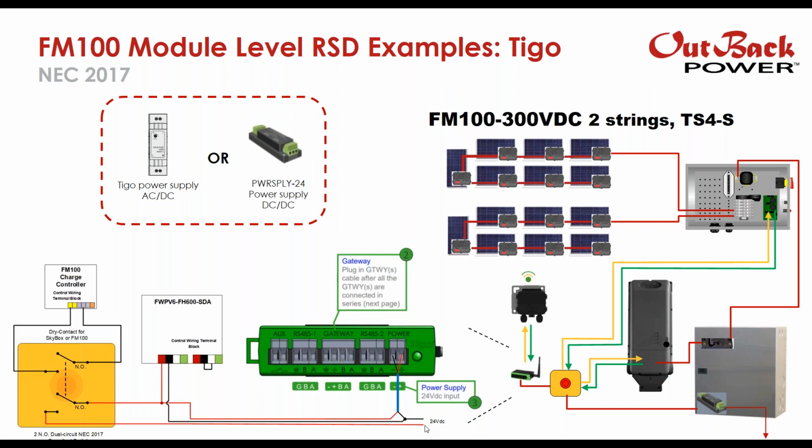So here we have our 24 volts, and we have our DC minus here. So you would be essentially removing power or providing power to the combiner box and also to the Cloud Connect Advance. And so removal of 24 volts is the signal for a rapid shutdown event. Okay, so then here you can see that we have the power supply. We're using the DC to DC converter that is powering the 24 volts. And then you can either remove the 24 volts or supply the 24 volts.